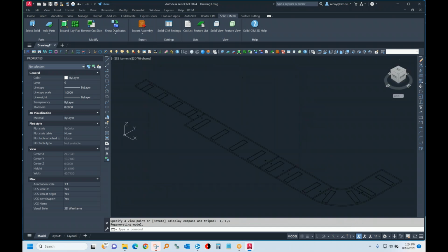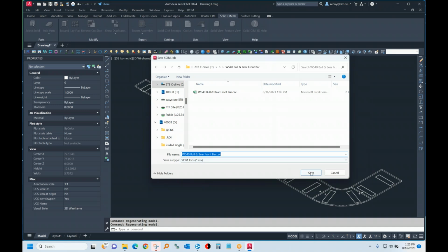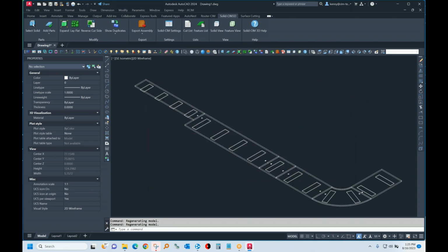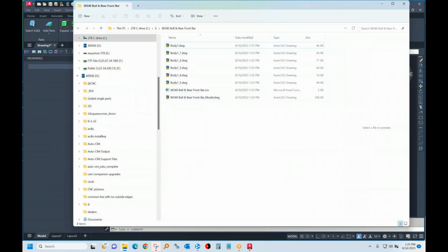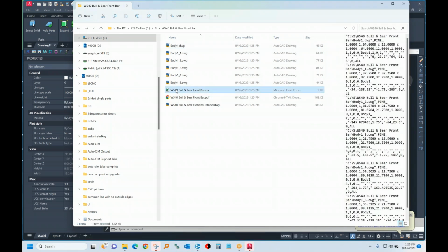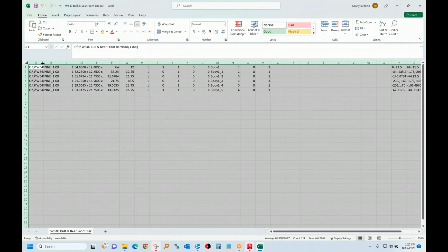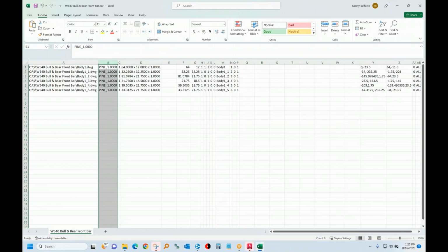And so that's the other click. So it's one click inside Fusion, then another command inside AutoCAD. It makes these as layered drawings or DXF files, and then creates a cut list for us. And here you can see it picked up the material. It was on a pine material, so it called it pine, and there's the quantity of each. There's the panel dimensions of each.